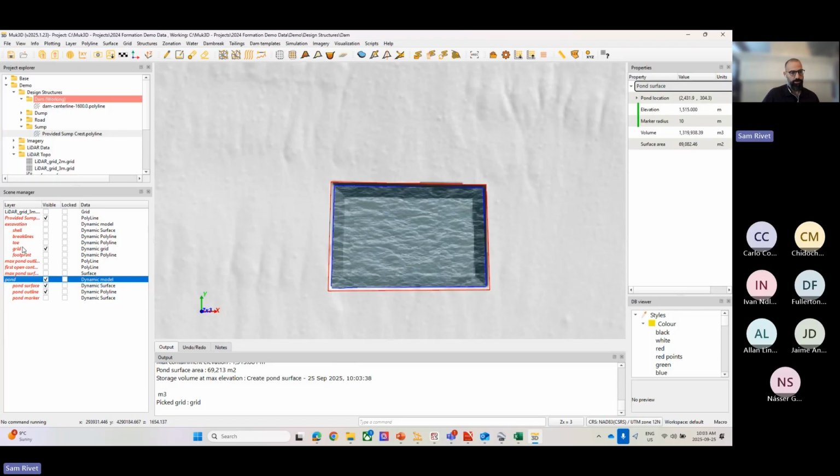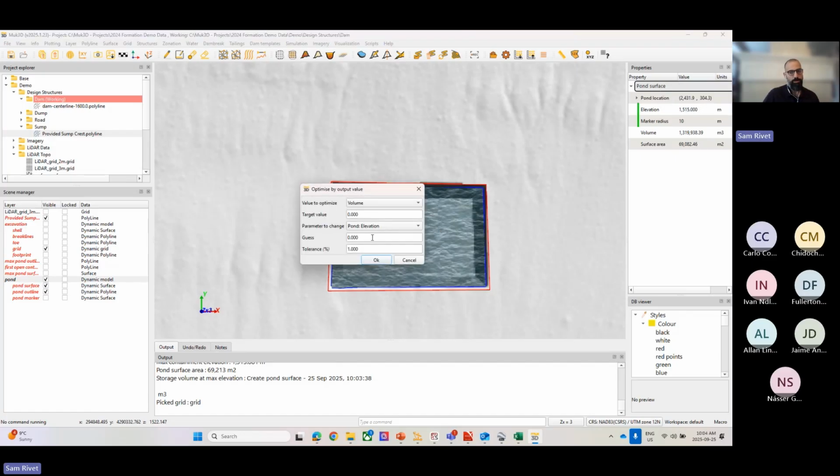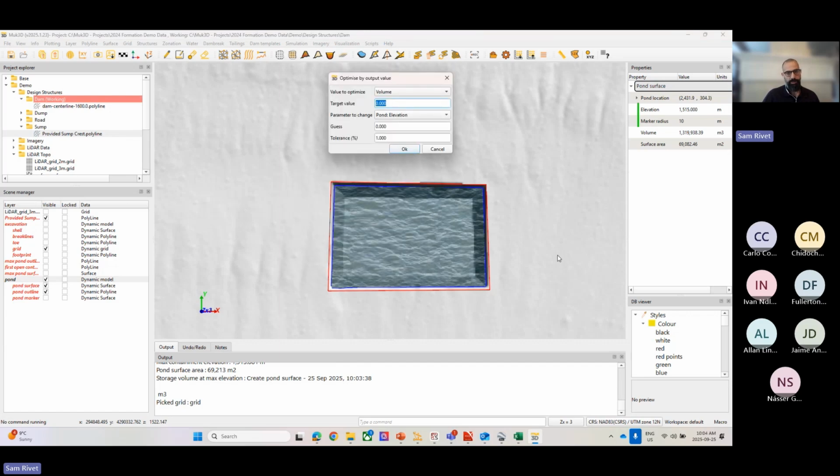All right, so I go back to my excavation, going down at 1 to 0. I'm going down 30 meters, and that's giving me a storage capacity of 1.319 million. So now I want to hit more pond volume. I want to bump that up to 1.45 million. And to do that, I want to excavate deeper. So I'm going to change the shell height, which is, in this case, the depth I'm excavating. I think it's currently 30, so I'm going to guess 30 and hit OK.